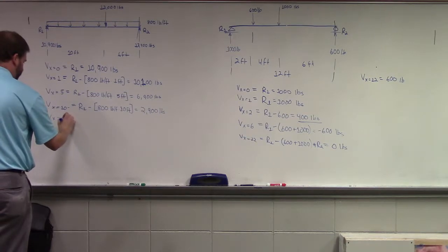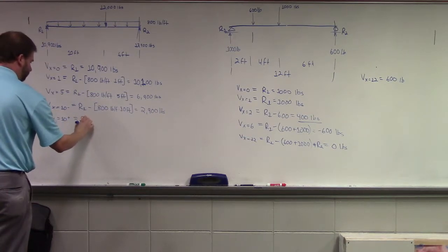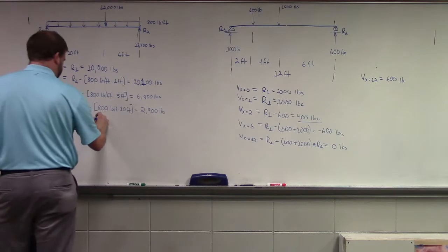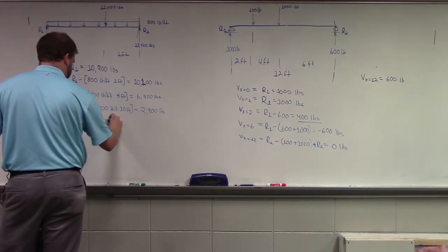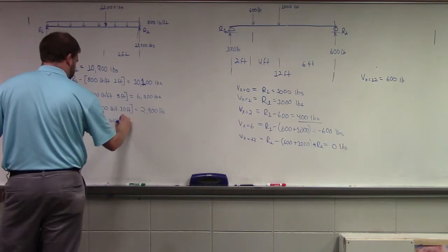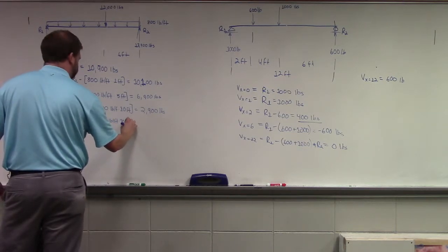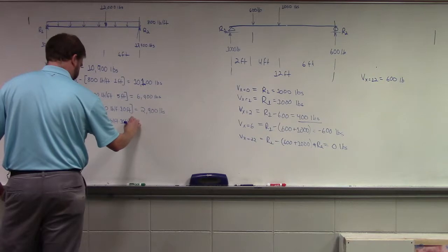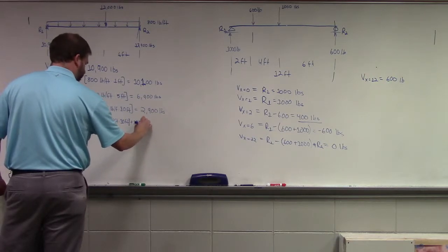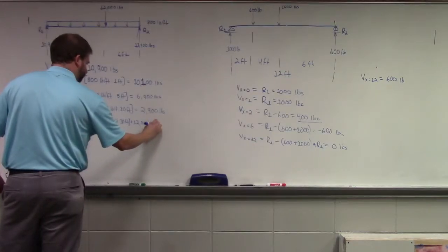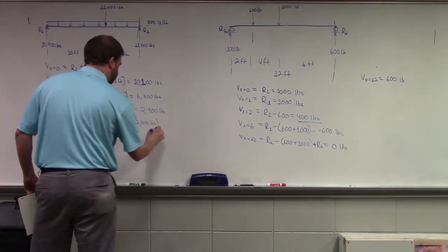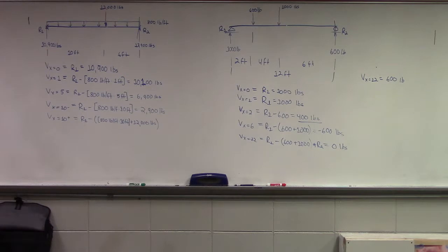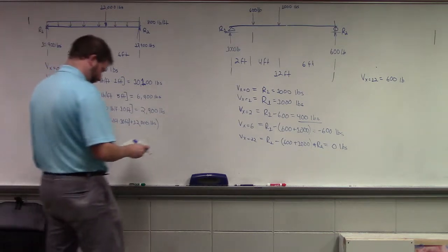Now, if we look just past the force, but we're still at 10 feet, what would we have? It's the same thing, but then you subtract another 12,000. Because 10,900 was going up, positive. Keep in mind what the sense is on your forces, right? So 2,900 minus 12,000 pounds is negative.